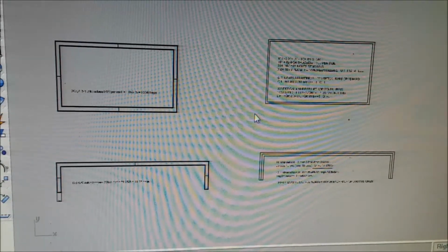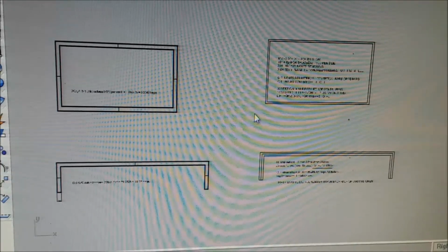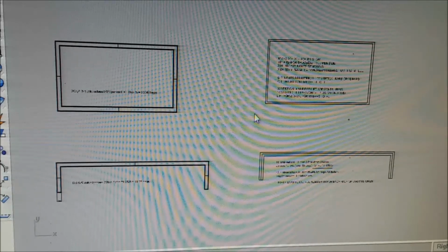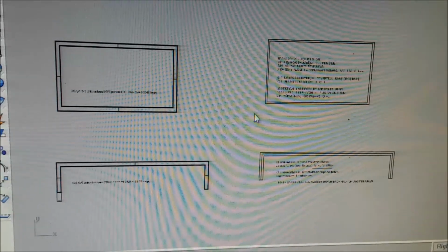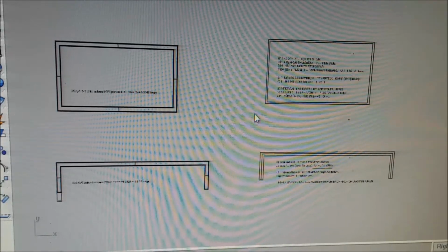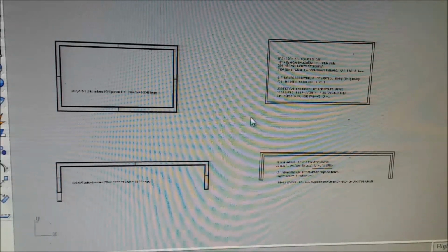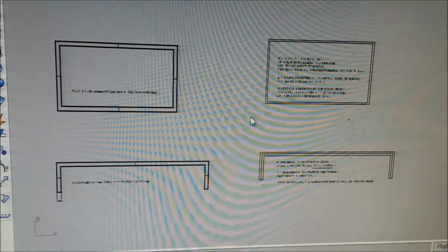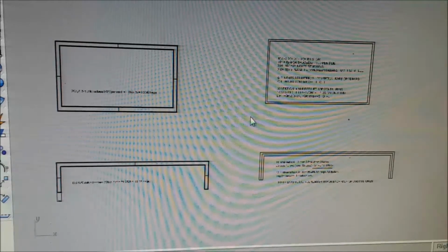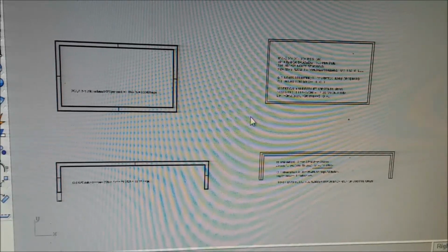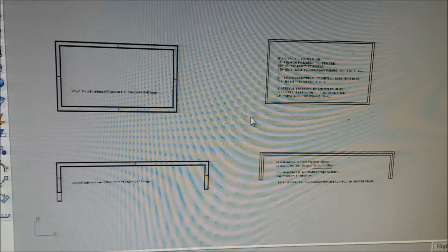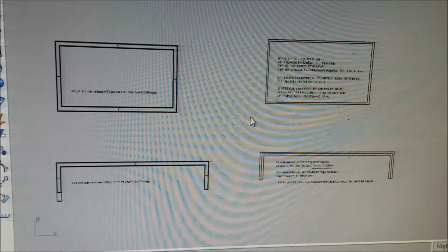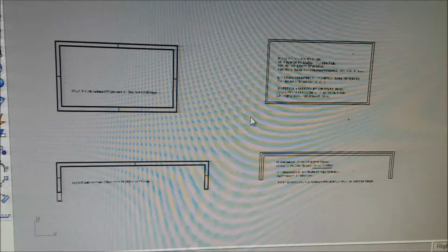4 parts sand, 1 part cement, and the concrete is instead of 1 to 4, it's 1 to 5. It's 2 sand, 3 rock. So your cement goes down, because you're putting all your cement in render and filling cores of block, and you don't have that with poured concrete. And you haven't got to spend the time it takes to get all that render on the wall. And that takes a fair number of people and a long time. It's painfully slow. And then once you get that, everything's the same.